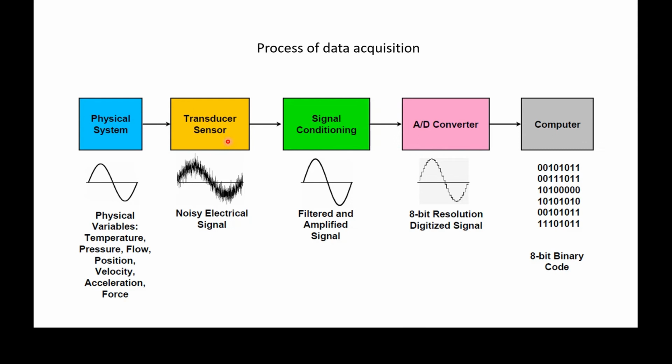We may have something like a flow transducer, which when you blow through it, provides you with a signal proportional to the flow. There are various kinds of things you can do. You can put a little miniature turbine in it so that it spins, and we can pick up its rate of spin as proportional to the flow through it.